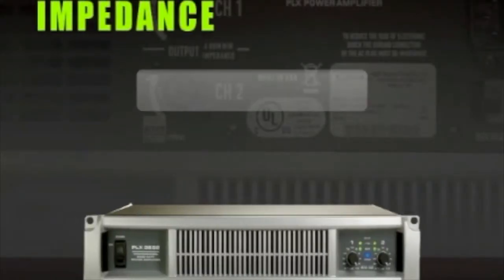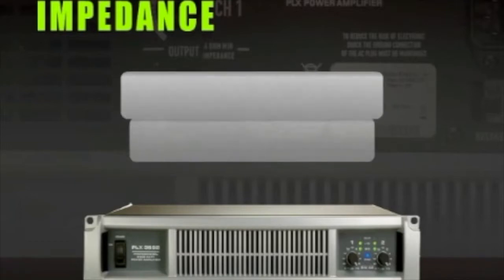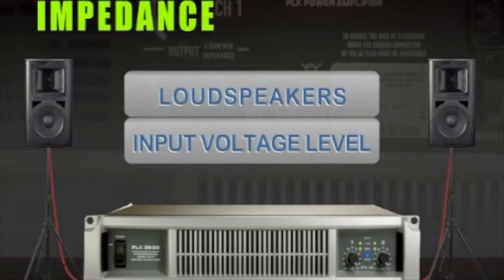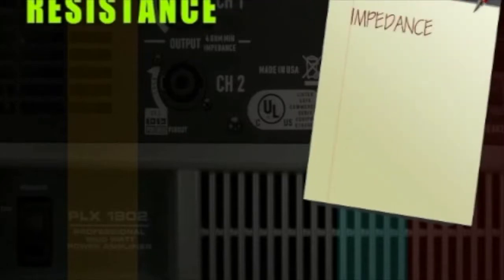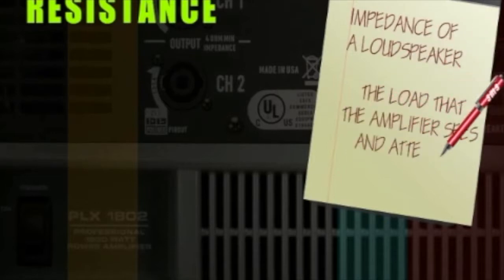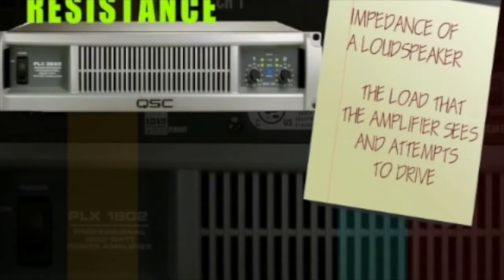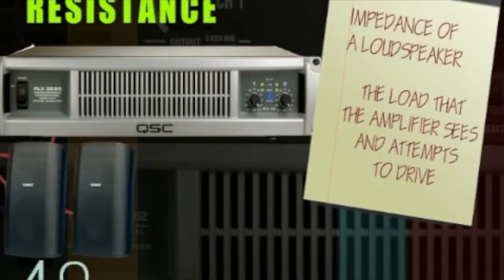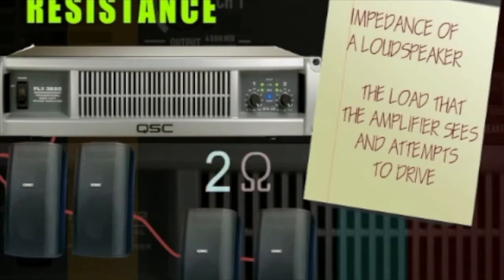An amplifier's output is dependent on the impedance load of the connected loudspeakers and the input voltage level. Impedance is the audio term for resistance. The impedance of a loudspeaker is the load that the amplifier sees and attempts to drive. Most amplifiers maintain stability driving loads down to 4 ohms, with some remaining stable down to 2 ohms.